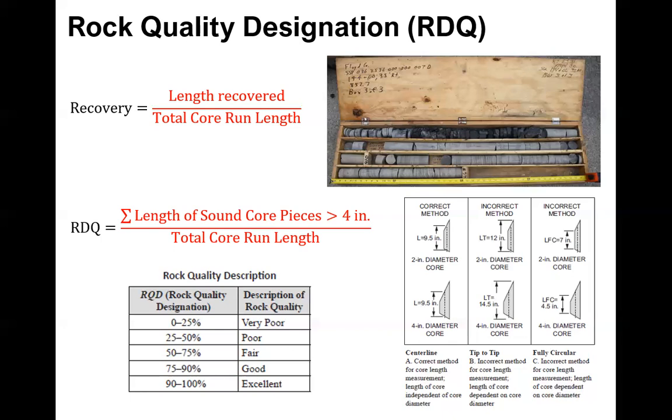So they may still take a sample and bring it to the lab and actually break it. These are little cylinders, so they could put it in a compression test and do an actual test on it. But they'll also calculate these values.